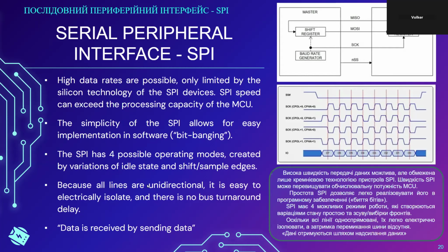And if you clock, generally, you can clock these shift registers as fast as the implemented silicon technology allows. That means on some devices, you can clock these at 10 megahertz, at 20 megahertz, at speed rates where a standard, for example, an 8-bit microcontroller, cannot make use of data that's coming in at 8 megahertz.